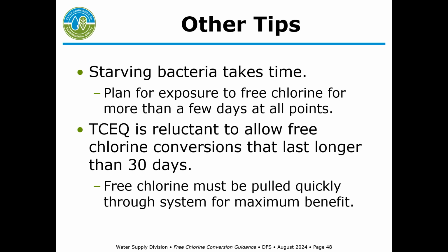Just keep in mind that we at TCEQ are reluctant to let you do free chlorine conversions for longer than 30 days. If you've only got a max of 30 days to do the conversion, you may need to do your flushing really efficiently to minimize how long it takes to get everything turned over and turned back, so you get the most amount of time with everything exposed to free chlorine.